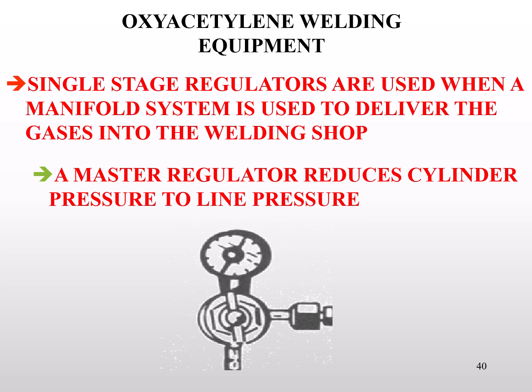In the lab, you won't see dual stage regulators at each work location, and the reason is we have a manifold system. We'll set our main pressures outside, then inside we will have a single stage regulator where we just adjust our work pressure. Once again, it's obvious that this is a single stage regulator because there's only one gauge on it. When it only has one gauge, that's our work pressure gauge.